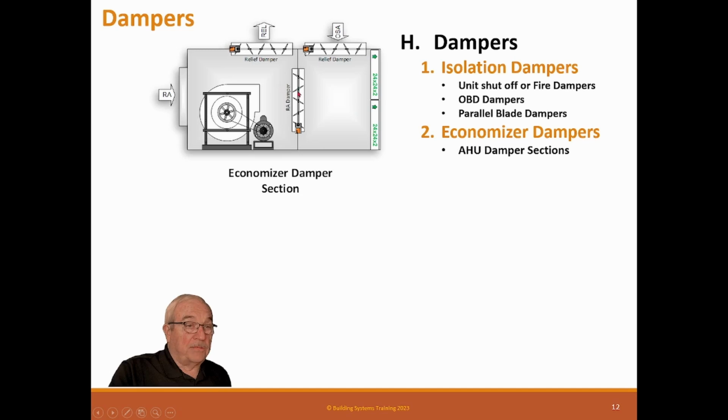If we're in economizer mode, this damper's closed. So all the air coming in here has a fan that blows it all out in relief air, and the air handler, the supply fan, sucks in all the air out of the outside. Now there's different configurations of how to do this fan, but the reason we have a return fan is so this doesn't affect room pressure.